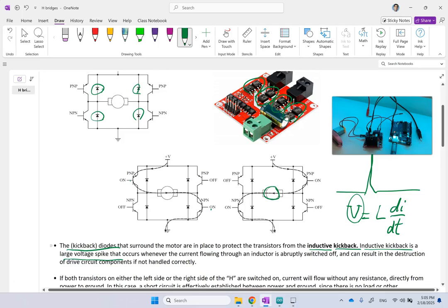So in order to stop that from going back into the motor and damaging the winding, what you do is you put these diodes, and as you know, and I will have a separate video on diodes, diodes are like a one-way valve, correct? Like a pass valve or check valve, you call them. So basically they allow the electricity to go this way, but not the opposite direction.